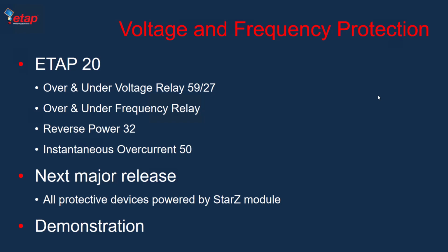So eventually all the DERs, based on the grid codes, will come to certain points where they will have more or less similar performance. But by that time, it would be beneficial to have a proper generic model that can do low voltage ride through, as well as grid forming and following for certain, let's say, microgrid applications when we want to be able to go islanded and come back. Most of these vendor models that we discuss don't actually support grid forming, as well as LVRT as per the latest grid code.